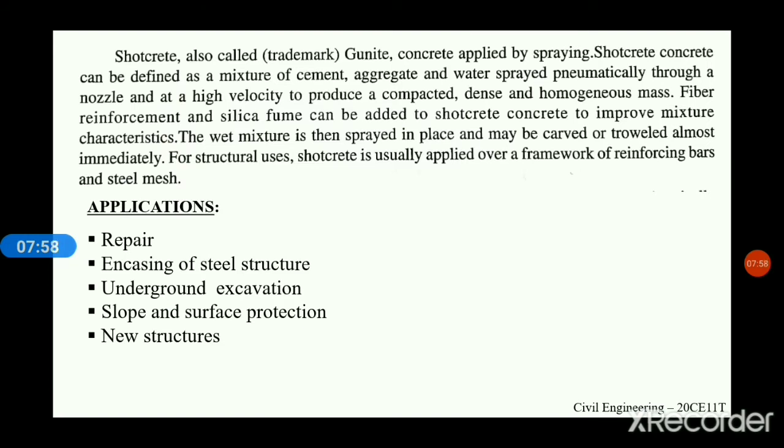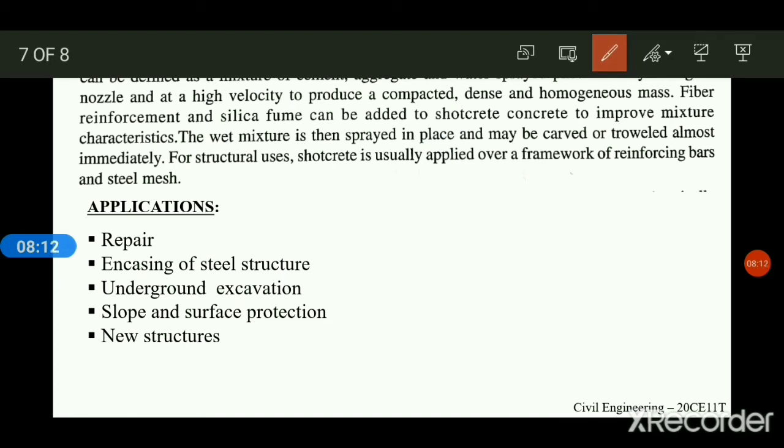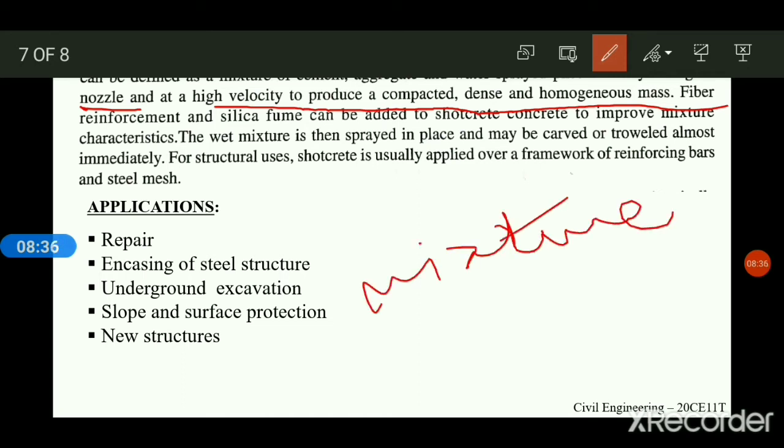So, I repeat, shotcrete can be defined as a mixture of cement, aggregates, and water sprayed through a nozzle with a high velocity to produce a compact, dense, and homogeneous mass. Fiber reinforcement and silica fume can also be added to shotcrete to improve the mixture characteristics.